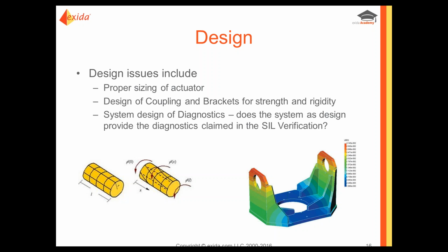Touching back on system design of diagnostics, when you did the SIL verification, did you claim credit for partial valve stroke testing? And if you did, then did you design a final element that really is doing that?